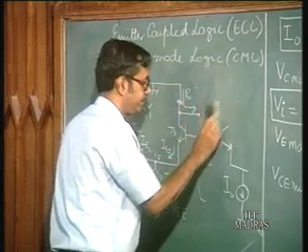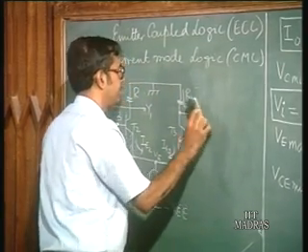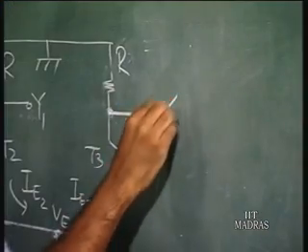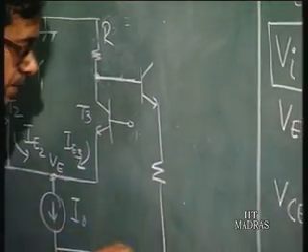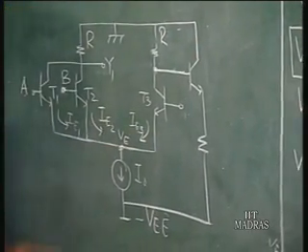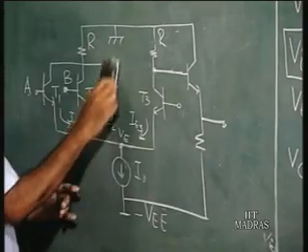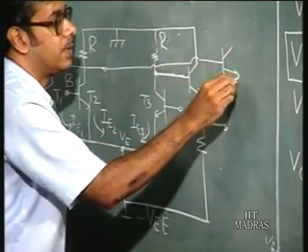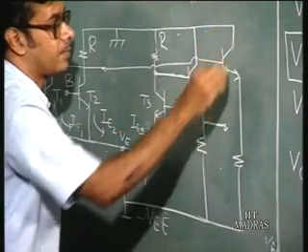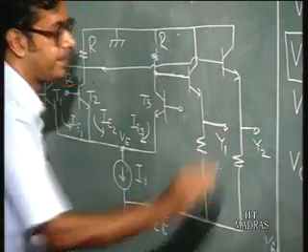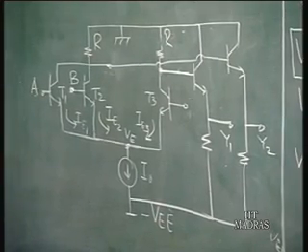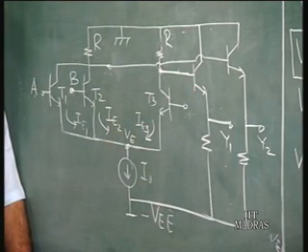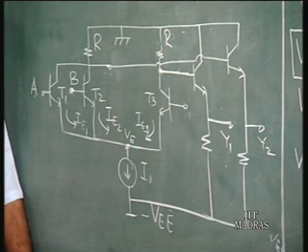Well, there is a very simple solution. What is done is, in this circuit, the output here is taken through emitter followers. So you have an emitter follower here, and the output is taken from this point. Here also, this output, you have another emitter follower. So these are the two outputs now. For the two outputs, they are now taken through emitter followers. Now what does the emitter follower do? It solves both the problems.